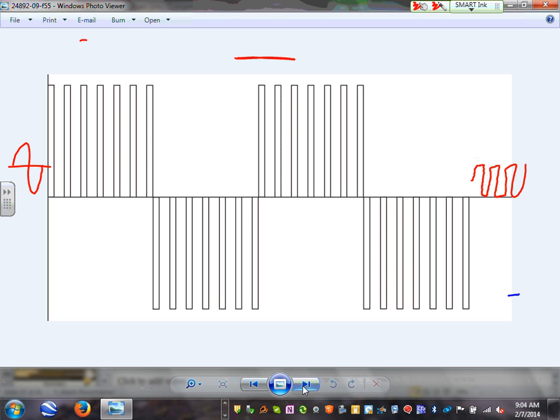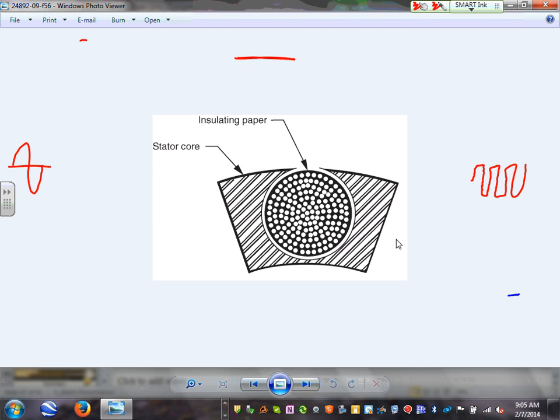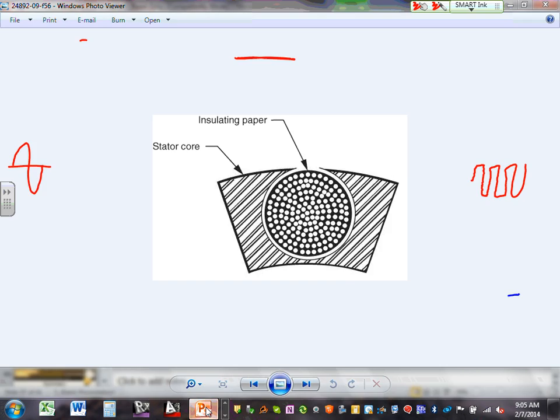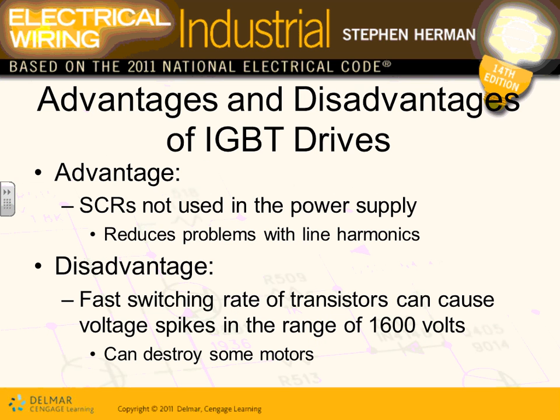Any comments, guys? Any questions about VFDs? VFDs take AC, convert it to DC, invert it back as different pulsation, and dump it across the motor. In the process, you can speed control that baby. Okay, so that's my VFD, which you guys will hear about all the time.